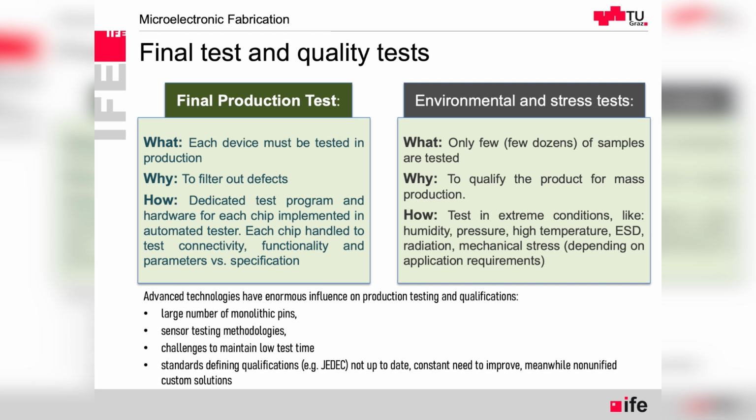Each chip will also have a dedicated test mode where we can access some internal parts which normally are not available in the application, but just for test purposes. For example, a function which should generate a certain current to generate a slope, for example for integration purposes, or a certain time generator, time interval, these kinds of things can be tested.